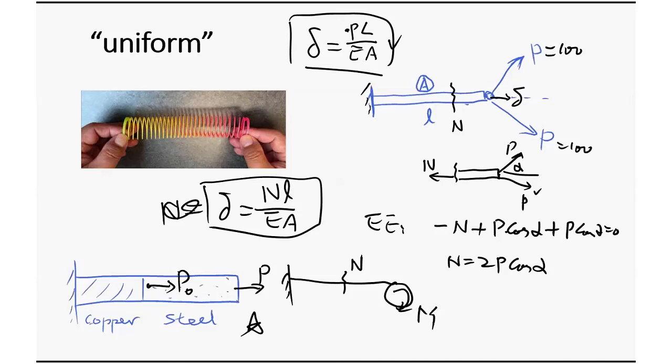Okay, any other questions? Because these are very important. Very simple things, but you need to set up the concept correctly, because otherwise, later on when you use it, you will get confused when things get complicated. How could N not be uniform? This is an example. If I apply load P0 in the middle, then it will not be uniform. All right. Or if you count gravity, right? This is the gravity direction. Gravity is pulling, so more weight builds up, and then it's not uniform at every point.